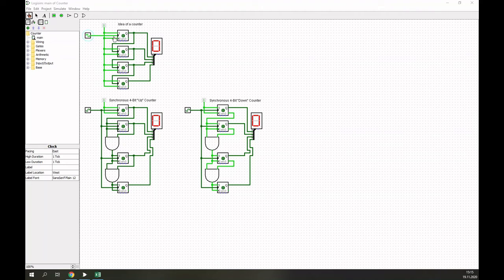If I use the clock directly here, the output is the input of the next, and so on, so that I have a connected sequential count up. And if I just use the output as a clock of the next input, what would happen? You will see directly. I start with 0. If I do the next clock, I get F, E, so I get a down counter.